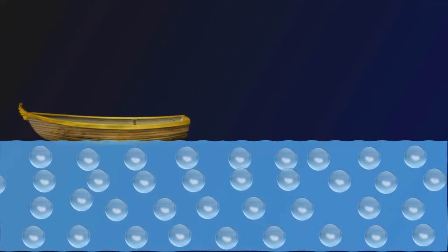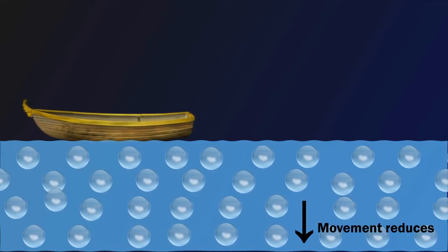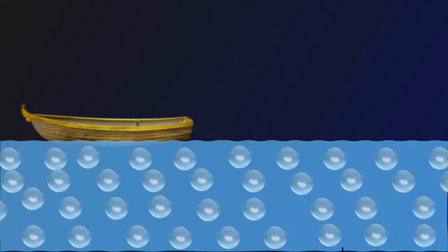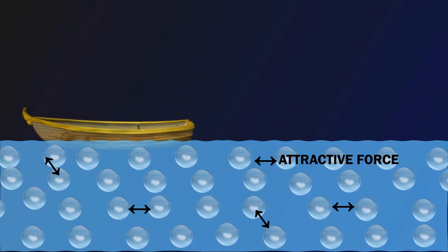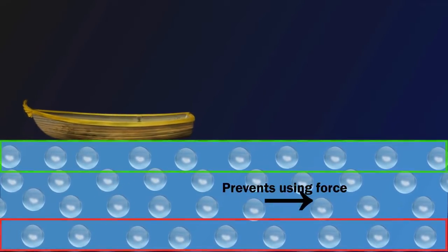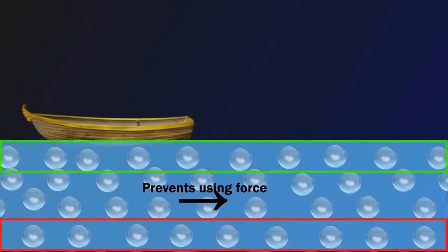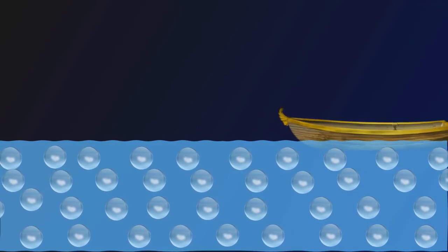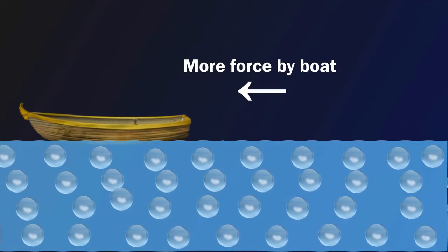Flows in which the frictional effects are significant are called viscous flows. However, in many flows of practical interest, there are regions, typically regions not close to solid surfaces, where viscous forces are negligibly small compared to inertial or pressure forces. Neglecting the viscous terms in such inviscid flow regions greatly simplifies the analysis without much loss in accuracy.